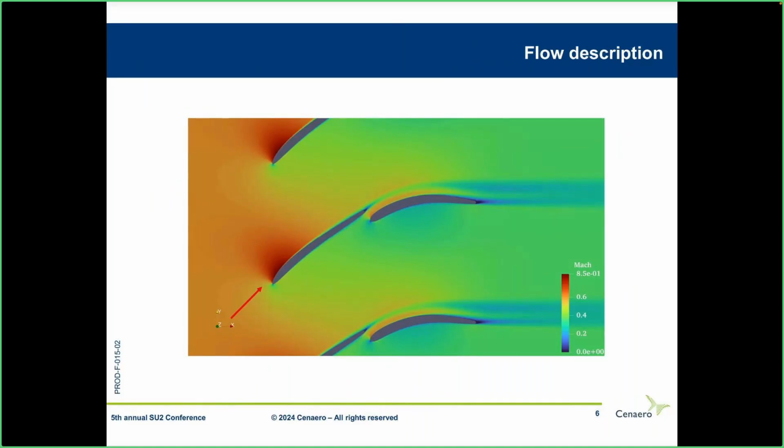And we obtain a flow field that here represents the Mach number. As we can see, we have a boundary layer that is attached on both blades. So we do not observe any separation, which enables us to have a higher turning with lower losses than if we were having only one given blade that was separated. Moreover, the wake of the first blade is constraining the flow above the second one, and it accelerates it, and then it mixes in the wake region.